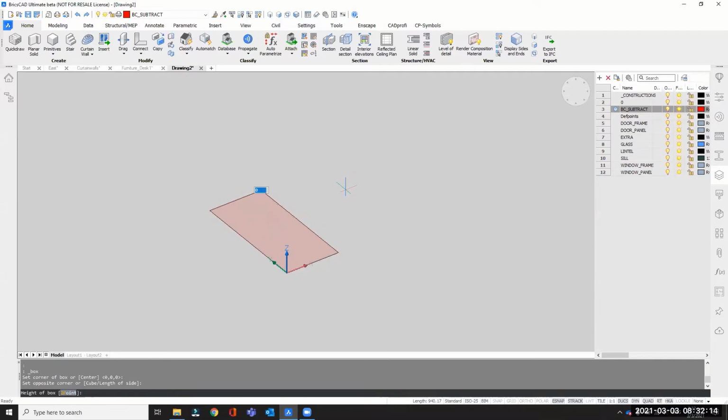The reason being, our starting point is 000, and that is actually the plane of the face of perhaps the building wall that we want to insert this component to. So as we go down, that means we are going into the building. Just imagine that if you go outside, you are actually subtracting outside the building, but that's not really important for us. We want to subtract inside the building. So we go downward. And in the training guide, let's just use 600 and follow.